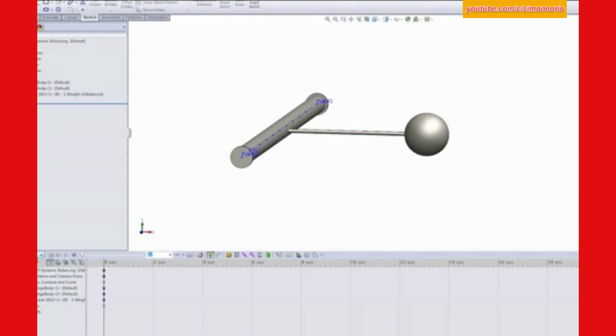This is what allows us to create or to analyze our assemblies and get out the kinematic results acting on our joints. As you can see here, it's basically a timeline interface. This is the SOLIDWORKS Premium interface, not event-based motion just yet. But as you can see, we have different options for calculating our studies, applying motors or springs, dampers, forces to our system, or even applying gravity. The option here, calculating results and plots, I'll go over that as we set up our first analysis here. And then, of course, as we're all familiar with SOLIDWORKS options, we also have study properties for our motion analysis as well.